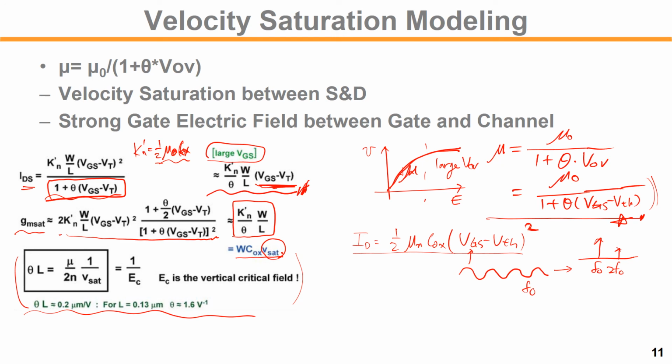So let's say you apply this signal onto your circuit and then measure the spectrum out of that. You are supposed to see only the second order and fourth order, like even order harmonics, ideally. But in reality, you will see third order harmonic, 3F0, there as well.